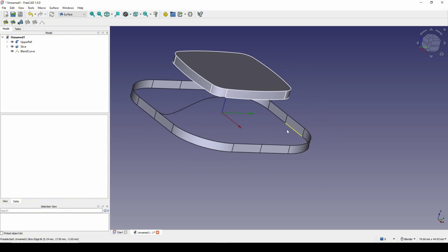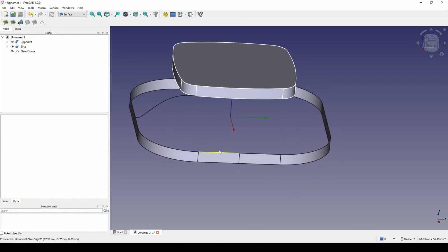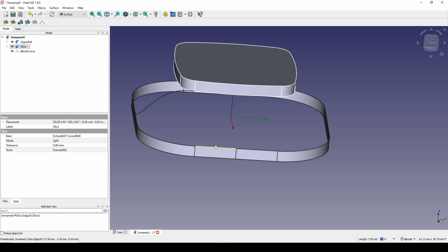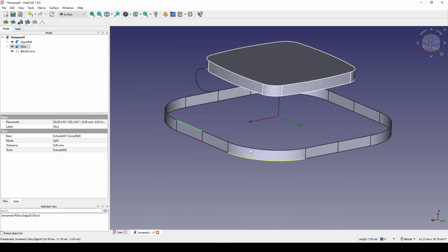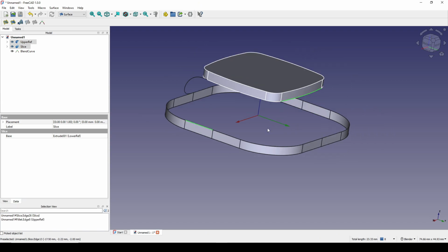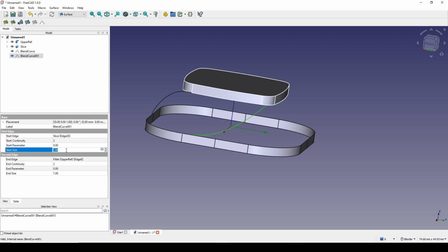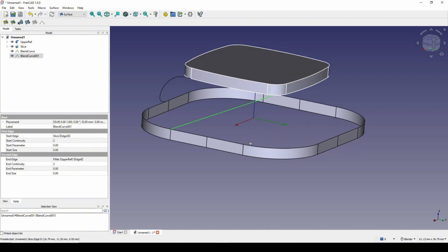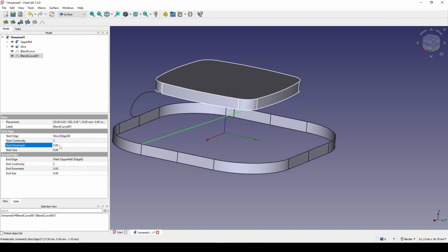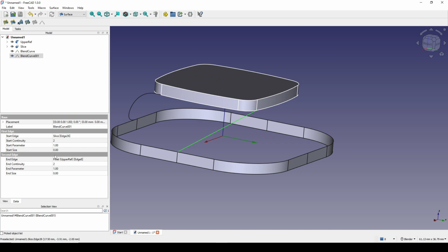Now I go to the right view and again Ctrl-select the edge on the left and another edge on the upper right and create another plane curve. Click on the plane curve and zero out the start size and the end size. Also doing the same, putting the start parameter to 1 and end parameter to 1. Put 1 for the start size, 1 working fine. The end size to 1, 1 not good, so -1.